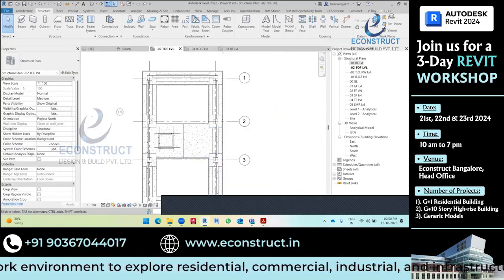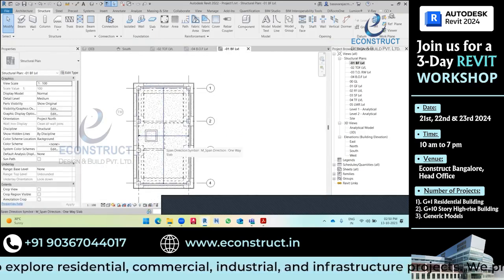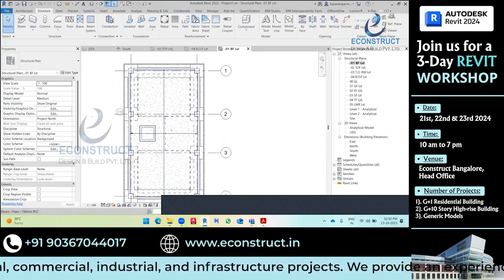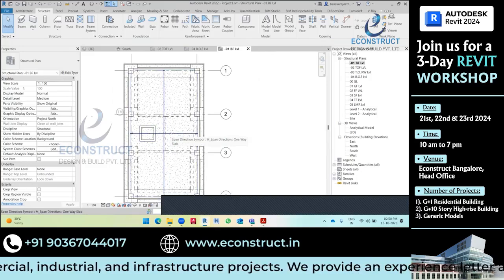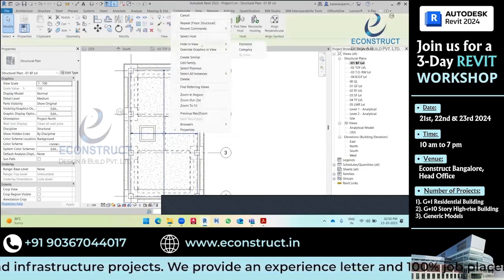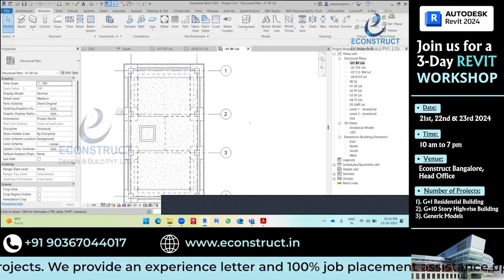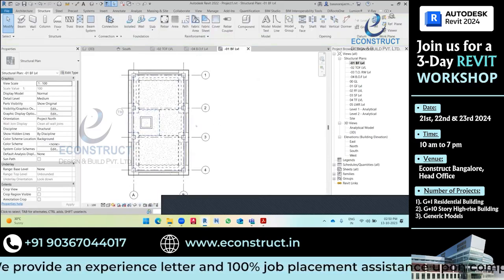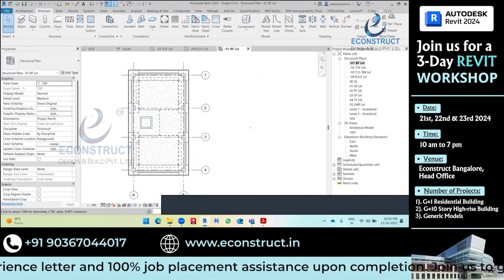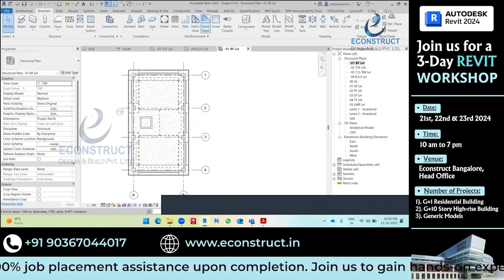See, now I will go to that basement floor level. Now this span symbol is coming, the span direction symbol. If you move your cursor over that, it will highlight. Just right click on that one, go to hide in view, elements. It will hide. So now some people are asking about view range. I will just open my view range now. Just enter VR or else go to view.